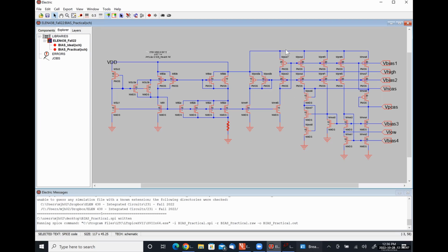This one over here has two transistors in series, but the drain of this one is tied to the gate of this one through that long feedback loop, effectively making that as small a voltage drop as is possible there. And so we see a larger amount of current flowing through it as well.